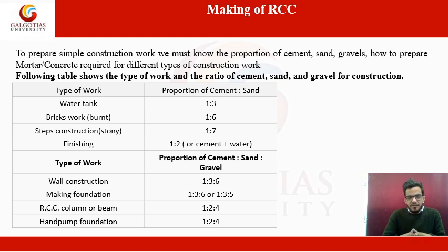While we are constructing work related to water tanks, the ratio should be around 1:3. While we are doing the brickwork, the ratio should be around 1:6.